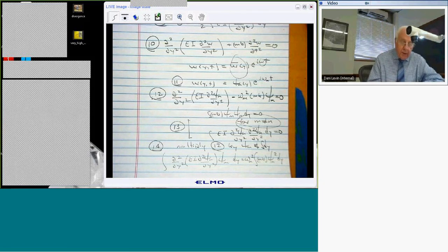Now, why is this a wonderful thing to have? It's wonderful because when I take equation 9 and express W in terms of these Eigen modes, I'm going to get something that looks a lot like this. In fact, it's going to look almost identical. And I'm going to use this result to write it in terms of omega_m squared and the integral over mass. That's what I'm going to do. Okay, let's see how that works.